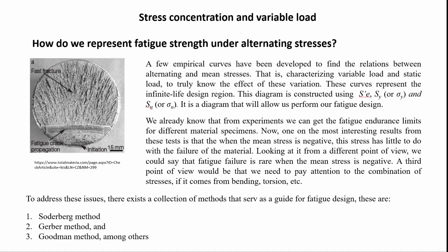Similarly to the static case, where for ductile materials we use the Tresca theory or maximum shear stress theory, or von Mises theory, and we could have the possibility of using the maximum principal stress theory that is also used in brittle materials, or the Mohr theory also for brittle materials. When we talk about fatigue, we could use a different approach or different theories. These three mentioned here are among the most used: the Soderberg method, the Gerber method, and then the Goodman method, and modified methods are also used there.